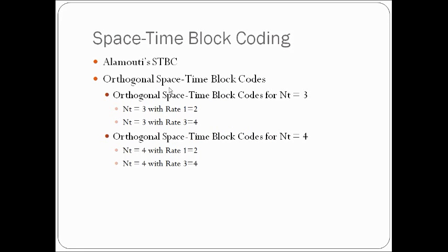Space-time block coding. Spatial diversity can be used in MIMO systems to fight fading in the channel, and this can be done via transmission of multiple copies of the same information via each channel, which ensures the probability of information loss drops exponentially. MIMO system antennas could be used to transmit as a SISO system, as the target rate is that of the latter system. The count of independent signal receptions marks the diversity order or the diversity gain of a MIMO system. A system with NR receive antennas and NT transmit antennas has complete diversity gain equal to NT×NR.